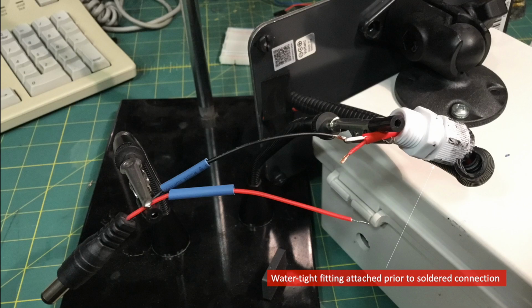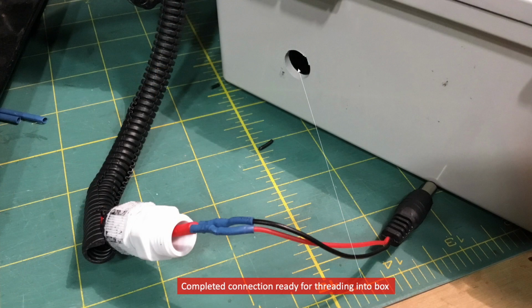Before soldering the barrel jack leads to the solar panel cable leads, make sure to add shrink wrap on the barrel plug wires and also attach the watertight fitting on the solar panel cable prior to soldering. Once the leads are soldered and the shrink wrap is attached, this is what your completed connection should look like, ready for inserting into your box.